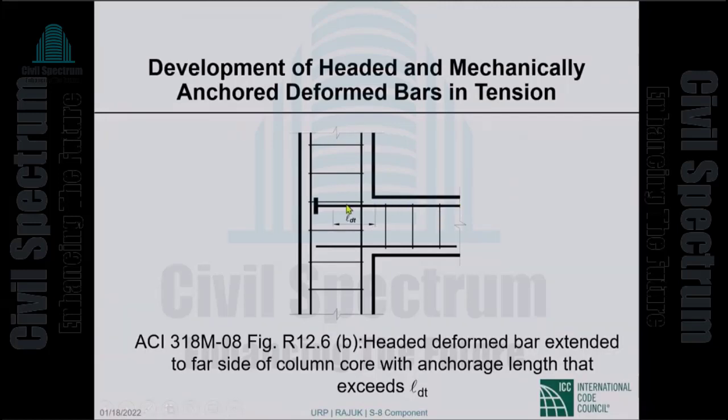Let us say you are developing that bar. L sub dt. So there has to be full development beyond the face of the column. If you are using a head, L sub dt will take you up to here. So you can terminate the headed bar here.